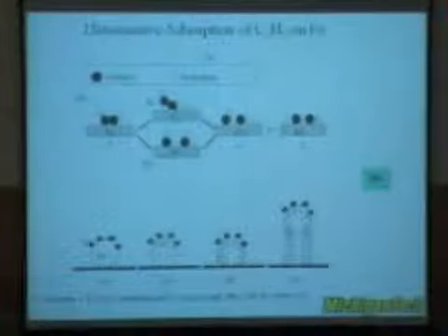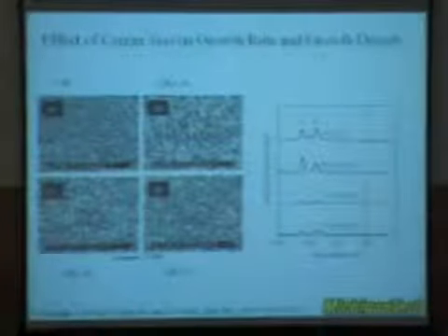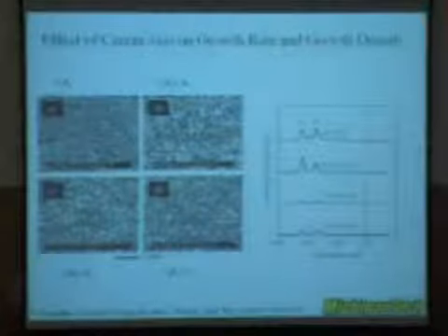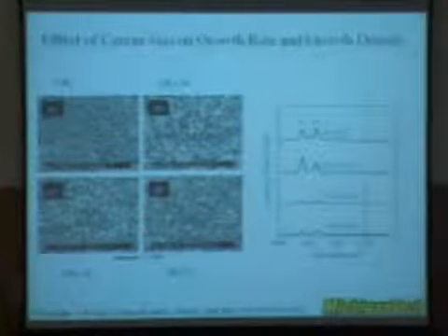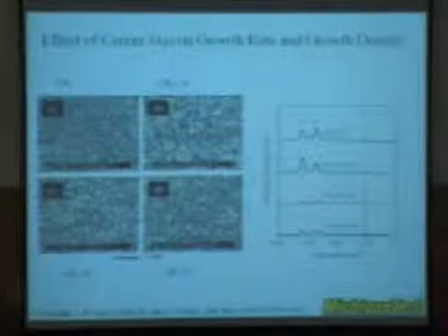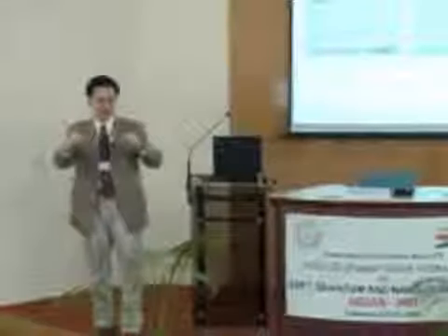By understanding some of this technique, we are already able to control the so-called density of the tubes. What is important for the most effective growth is that you have to make sure that all the catalysts, it might be 1 trillion pieces of catalyst at this size on the chip, will grow effectively.